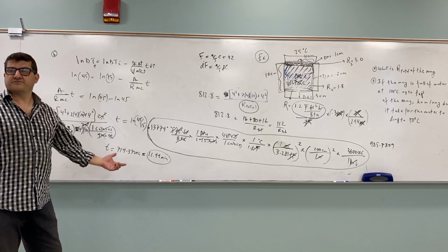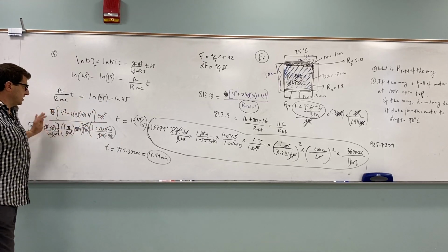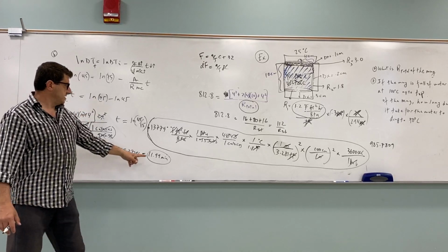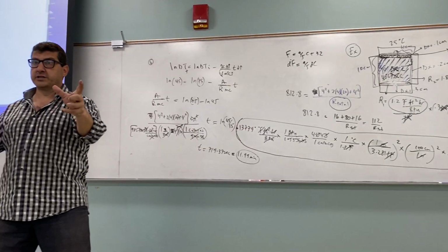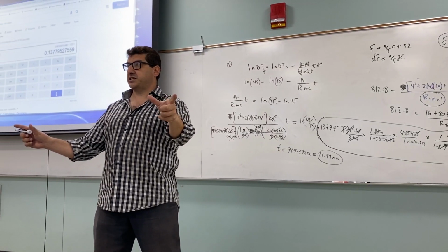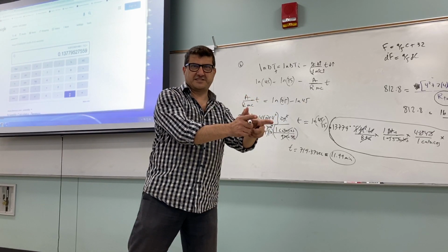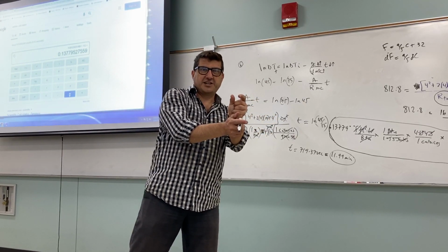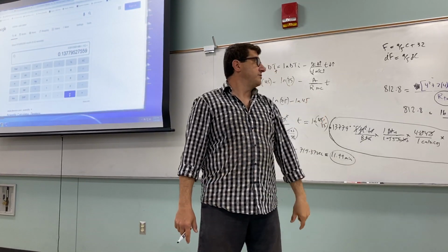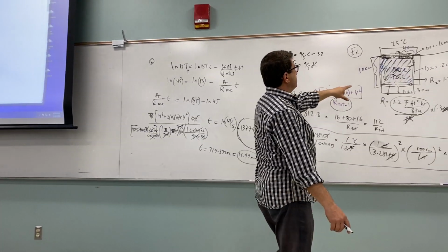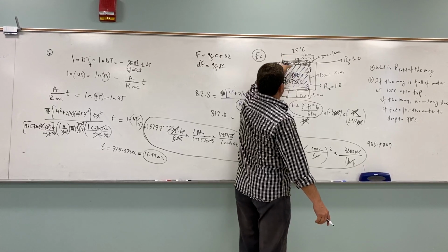25.79. So I just guessed 25 minutes, you see that? Because everything else is the same, the area, the R value is the same. The next from 70 to 40 should take 25 minutes. So in total, it takes 36 minutes to drop to 40 Celsius, you see? But the first 30 takes 12 minutes, then after that, 25 minutes. Well, there's no next 30 because the temperature of the outside is 25, so you just have 15.